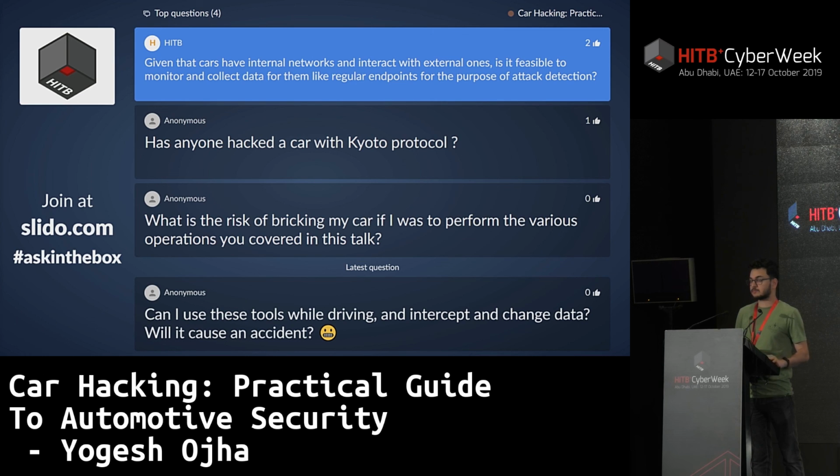What kind of fixes or countermeasures would you recommend against these attacks? One of these fixes could be using encryption, so that having a private key in one of your small hardware chip devices, once you have the encryption, it's really difficult for you, without getting the private keys, to reverse engineer them, right? And then the other thing that you can have is implementing the IDS and IPS so that you could not inject the fake packets from the OBD ports. That could be one of the possible solutions for this one.